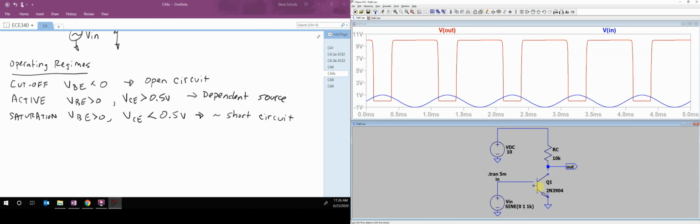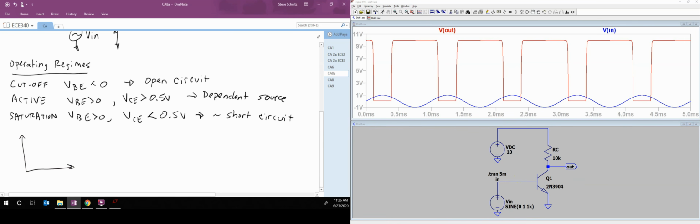Okay, so now if we put this back in here, now we're going to look at this case. Well, in this case, it's 1 volt. I'm above the threshold condition, so it's going to have some current. If we remember, if I look at my IC versus VBE, it acts as a diode, so it looks something like that. And this point here is about 0.7 volts. If I'm putting in 1 volt, you see it has a really high current.